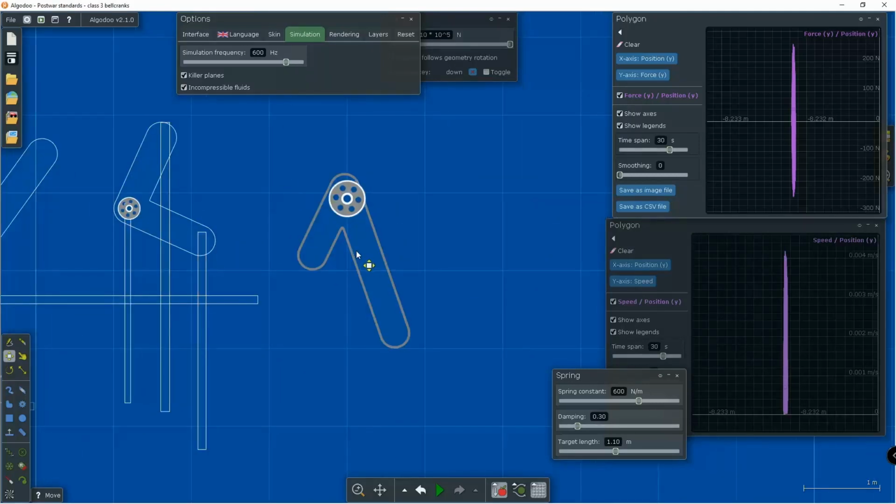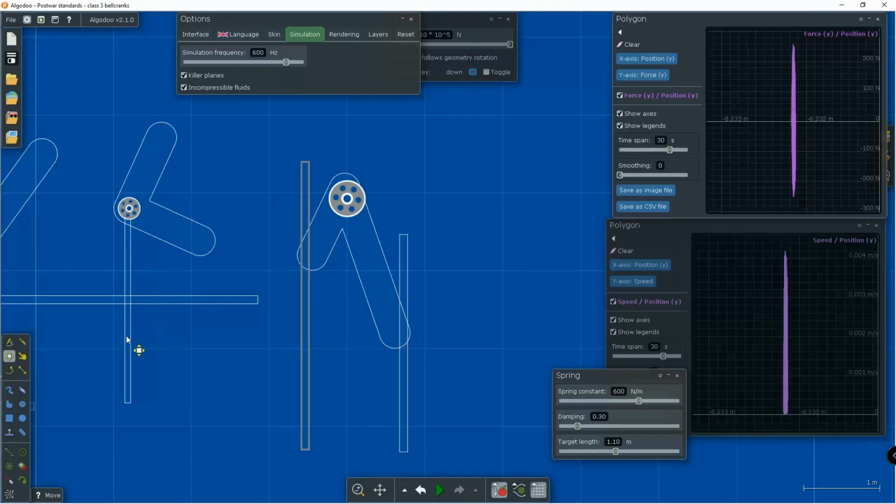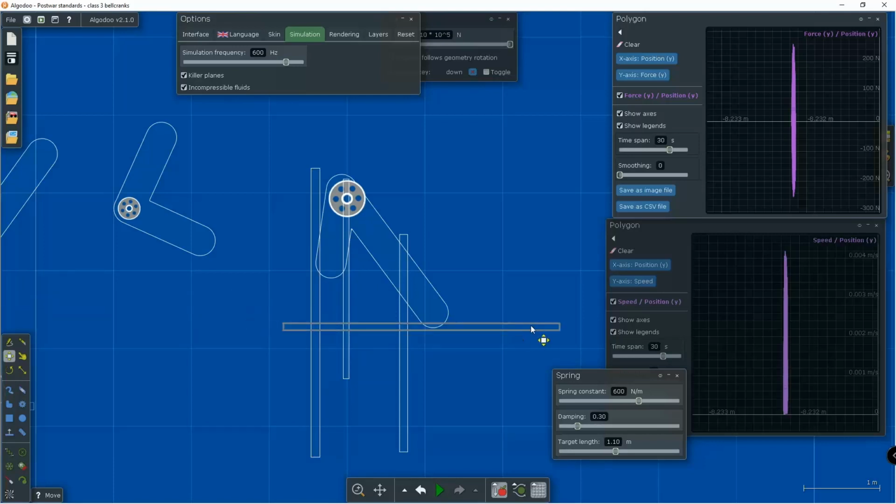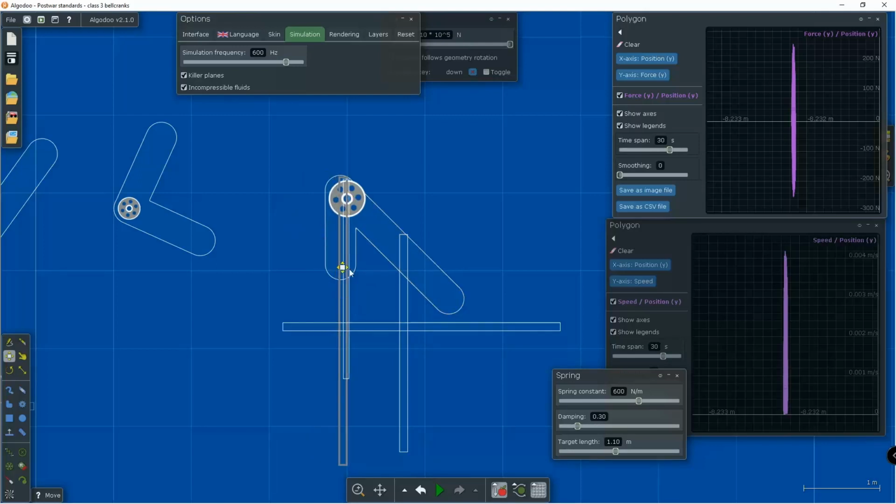The same goes for this Bellcrank, which here has an acute angle. So say that our effort is over here. Right now, it's class 1, but if we rotate this, or more so, we are rotating the effort vector, then, well, if the effort is parallel with the effort arm, that is a degenerate case, where the effort isn't capable of actually causing any torque.